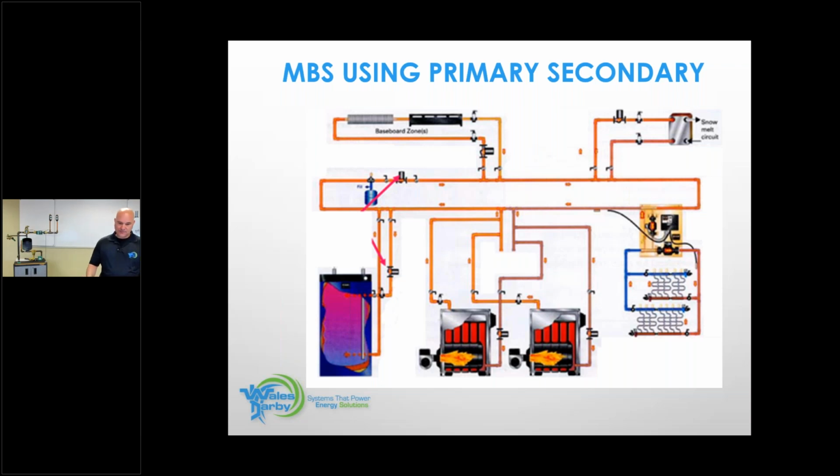So in this system, we have a primary, secondary connection here. That's for our boilers, and they are reverse return. So our boiler supply will go this way. Our hottest takeoff is primary, secondary. We have a circulator right here, and we have a circulator on what we're going to call the hot loop. So hottest takeoff first for hot water. We come around, pumping away from the expansion tank, and get to our baseboard circuit. It has its own circulator.